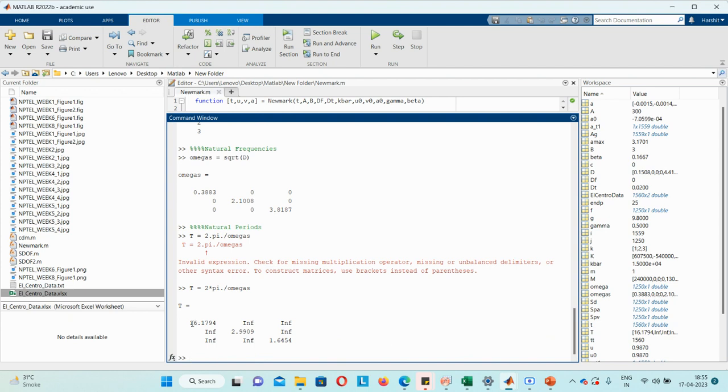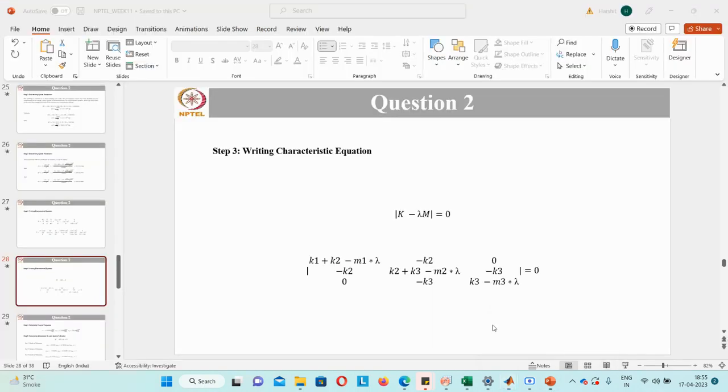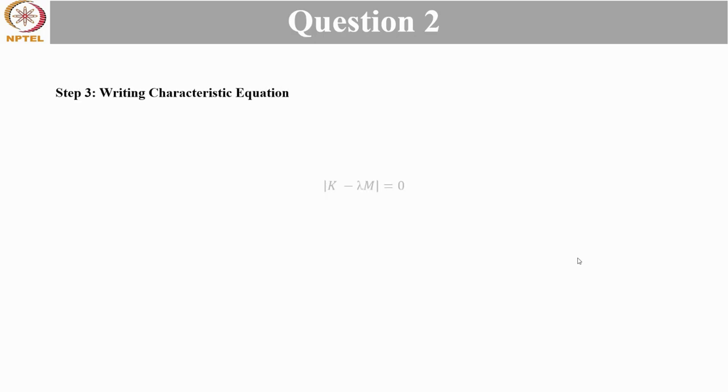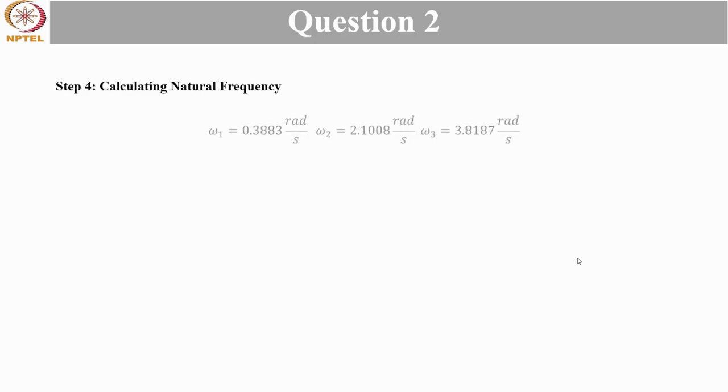Now we know the first mode of vibration will have the maximum mass participation, so this is our critical time period. But still, if we want to check which has the maximum time period, what you need to do from here is first obtain the deformation matrix for each floor. For that I will just move to the slides, and I won't write the code because we have that code from earlier lectures also.